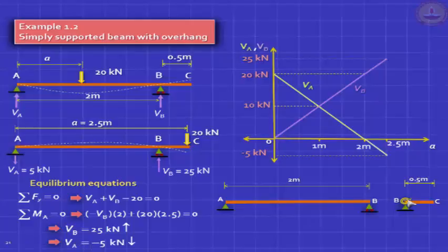If you want to know what is that rotational spring stiffness, it is like a door closer: if you apply more moment, it will move faster. If you apply less, it will be slower. So this rotational spring has a stiffness in terms of kilonewton meter per unit angle of rotation. You can find that out, but that's not an issue. I just want you to correctly show this.